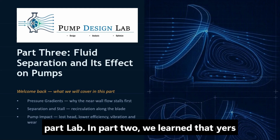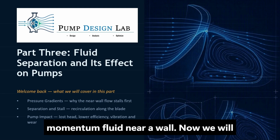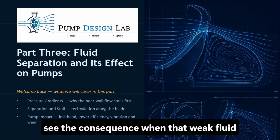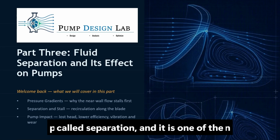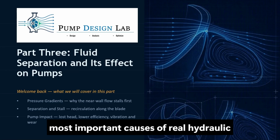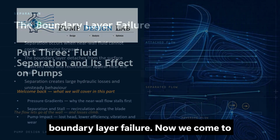In Part 2, we learned that boundary layers contain slow, low-momentum fluid near a wall. Now we will see the consequence when that weak fluid meets a rising pressure. This event is called separation, and it is one of the most important causes of real hydraulic loss. Separation, the boundary layer failure.